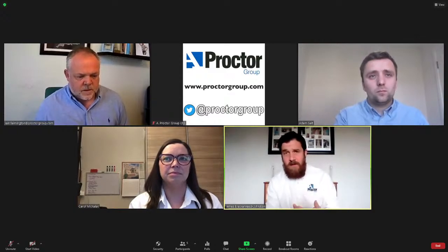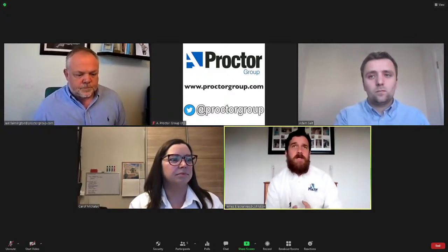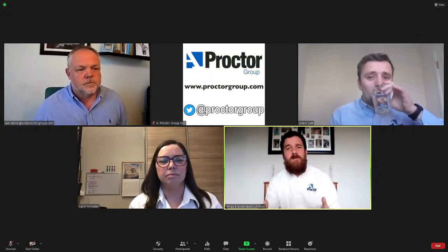Indeed, it's something that we assess, whether it's a new build project or a retrofit project. We'll establish the build up with you. If it's on the retrofit side of things, as Kira mentioned during the presentation, we'll carry out a WUFI analysis on that build up. And if a VCL needs to be integrated into the build up in order to make sure that the condensation risk is kept to a minimum, then that's what we'll do.